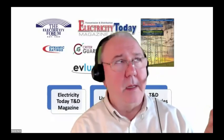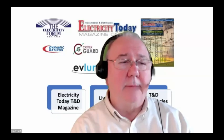Is there a possibility to have an online monitor, constantly monitoring the tap changers, or is it only done periodically? Well, in fact, it's a good question because we have developed exactly for this purpose the OTMX, which is an online monitoring product. This way you have your vibroacoustic and your motor current, and you can compare your events immediately.